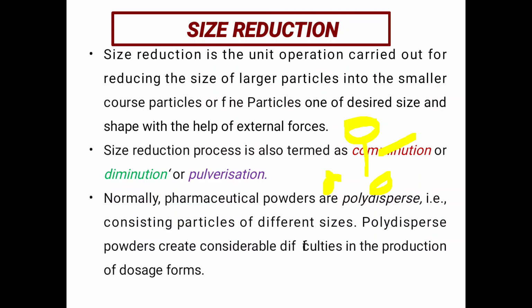Size reduction is a unit operation carried out for reducing the size of larger particles into smaller coarse particles or fine particles of desired size and shape with the help of external force. The size reduction process is also termed comminution, diminution or pulverization. Also remember, normally pharmaceutical powders are polydisperse, consisting of particles of different sizes. Polydisperse powders create considerable difficulties in the production of dosage forms.